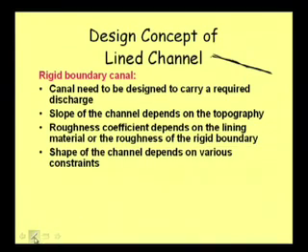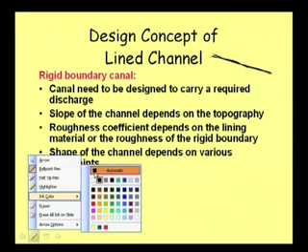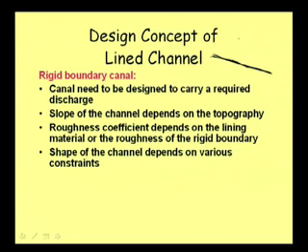Well, then similarly, sometimes you may find that a triangular shape is better for some considerations. But when it is a triangular shape, then we can see that, say this channel, suppose a triangular channel is otherwise better, but this angle may sometimes be very narrow, and if sediment deposition takes place in this part, it may be practically difficult to clean, and that may be one constraint.